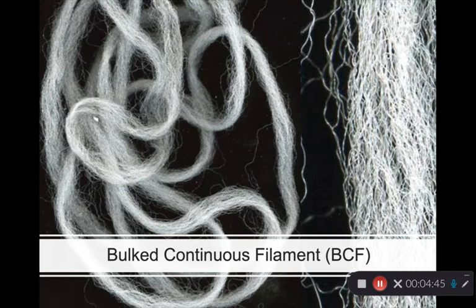As we know, your synthetic fibers can be bulked, meaning they can be heated and then shaped in a particular way and then cooled and hold on to that shape. Bulked filaments have the aesthetics and the comfort of a spun yarn. Compared to a smooth filament, bulking makes the yarn more absorbent, more permeable to water and air, and tends to be more comfortable along its length.